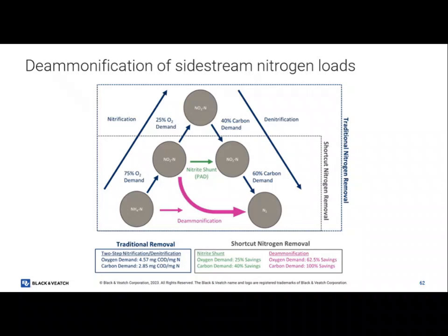So we test NO2 and NO3 4 to 6 times per day. And we're doing that because we're running such a fine line right now. We can have 0.5 loading and knock our chlorine dose rate down into the 5s, even 3s for dose rate. But if that nitrite starts creeping up, even with 0.5, 0.7, 1 part ammonia, we're at 7-8 times chlorine dose rate. Yeah, it spikes pretty quickly. Really have to watch that close.